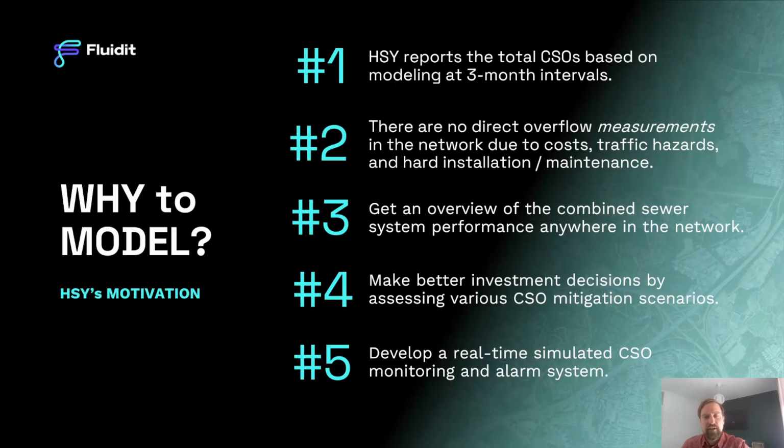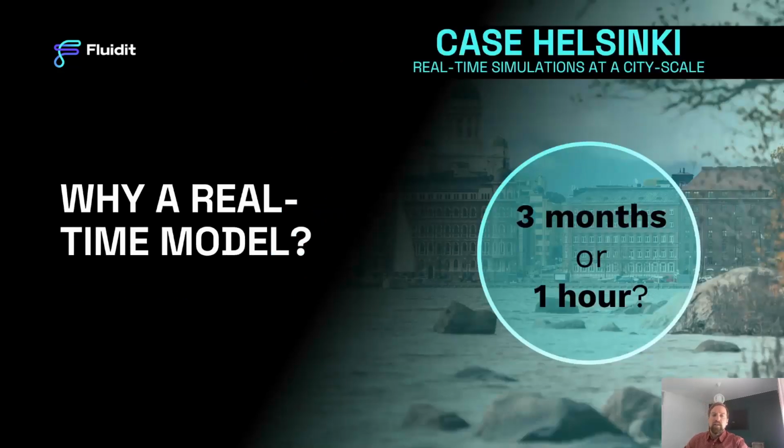Okay, so why would you need a real-time model? What's the point? Well, let's imagine that there has been a heavy storm in your city. Would you like to know about the severity of the CSOs within 1 hour? Or are you happy with knowing after 3 months? And this has been the case in Helsinki, as they only reported and properly observed the CSOs after 3 months as part of the quarterly simulations.